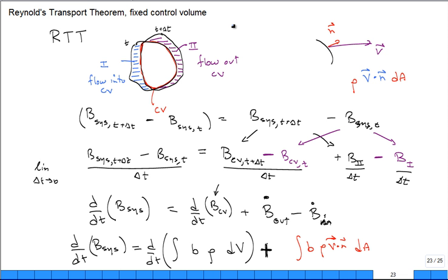All right, so what I'd like to do is give you a brief overview of the derivation of the Reynolds transport theorem. In all of these things, our conservation laws apply to chunks of fluid, matter, substance. But we like to think about a region in space where the matter sweeps in and sweeps out. The location of the chunk at some time, time zero, or initial time, or before time, okay? And then later consider some time where it's swept, okay? Then look at the overlap. The overlap is the focus of the study.